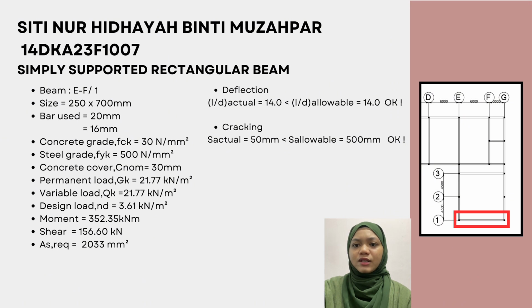From the calculation, the design moment obtained is 352.35 kNm, and the design shear force is 156.60 kN. The required reinforcement area for bending is 2050 mm square. Next, deflection and cracking check.